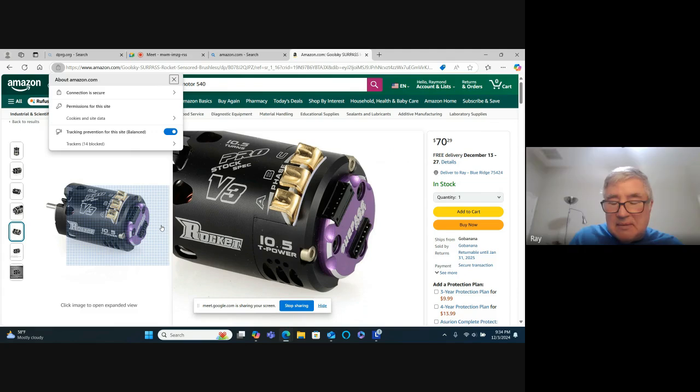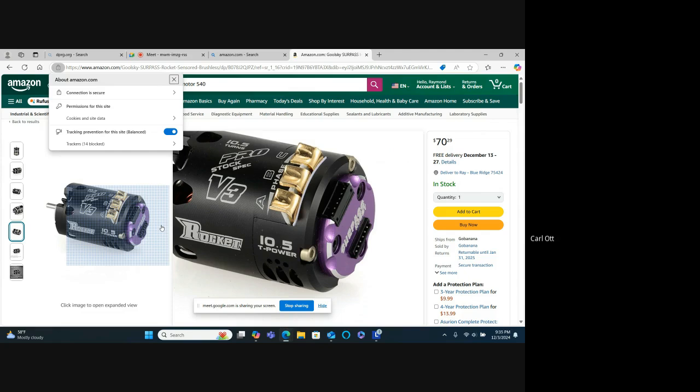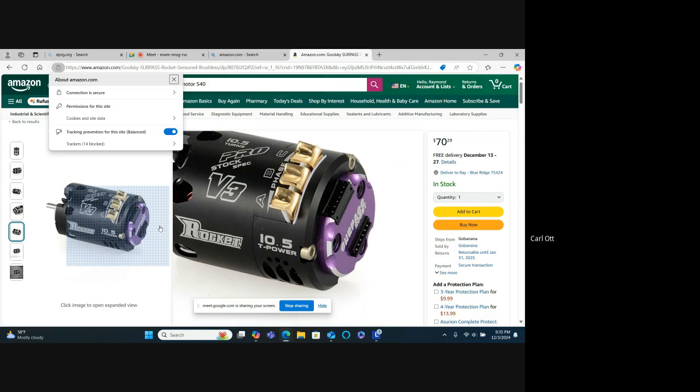Yeah. I'm assuming usually the Hall effects have 3 wires plus power and ground, so 5. But these are 3-phase, right? I think these have 3 halls in there. And I think if I remember reading just a week or 2 ago, I'll bet that's what that purple bump is on the back. You see how one connector feeds out straight to the right. The other one comes up towards the top. I believe they sell these because in different models, your wiring might want to go in different directions. And from what I've read, it's the same electrical pin, so you can just use whichever connector you want.